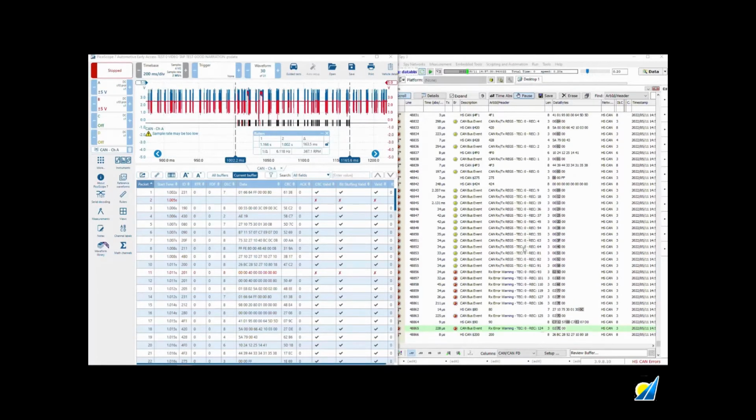Also notice there are no transmission errors, suggesting that no ECU is sending an error transmission. Above a certain level, I thought it was 127, but on this it's at 91, you see that we started to turn our errors into red. Now this suggests that the node has changed state. It's moved to error passive state. So it can still flag errors, but it cannot terminate messages. So it can still notify of errors, but not destroy the message on the bus.